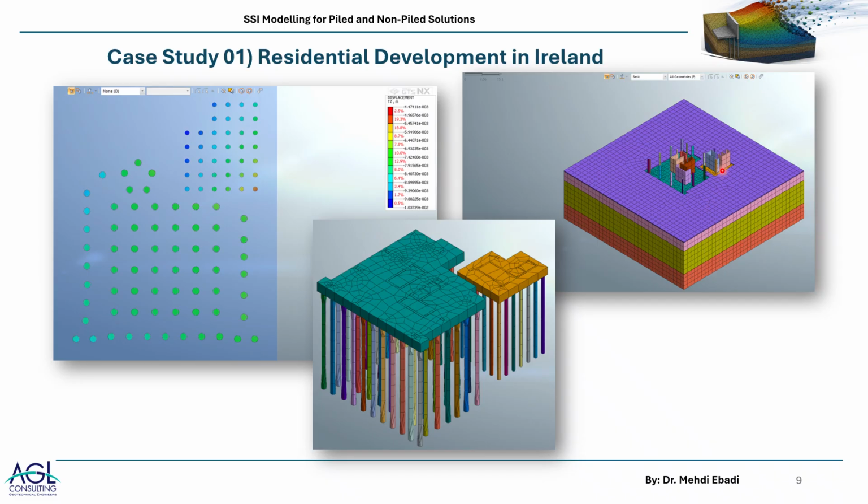We added the shear walls and columns of the basement floor so that we would have the rigidity of those elements in our analysis and the results. As you can see in this screenshot from MIDAS, we have the foundations as bulk elements.